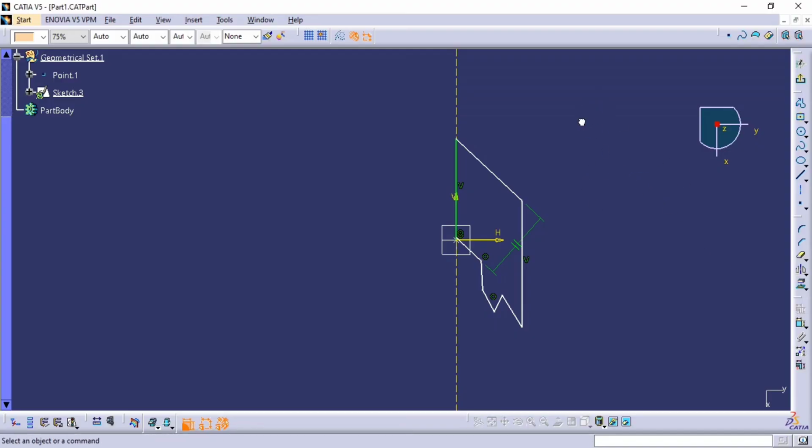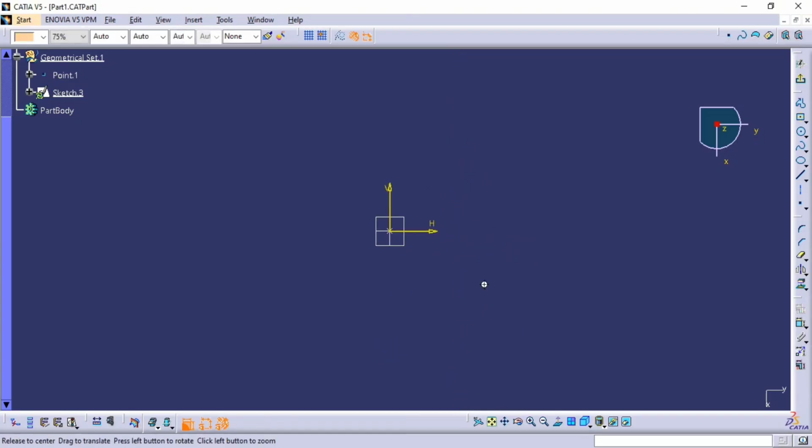So in SolidWorks, in the sketch environment itself, it is recommended to use translation, corner, chamfer, and circular pattern, rotate. The scale we won't even use, offset. So offset is one tool we use a lot in the sketching environment. Using translate and rotate features in the sketch environment is not recommended. Okay.